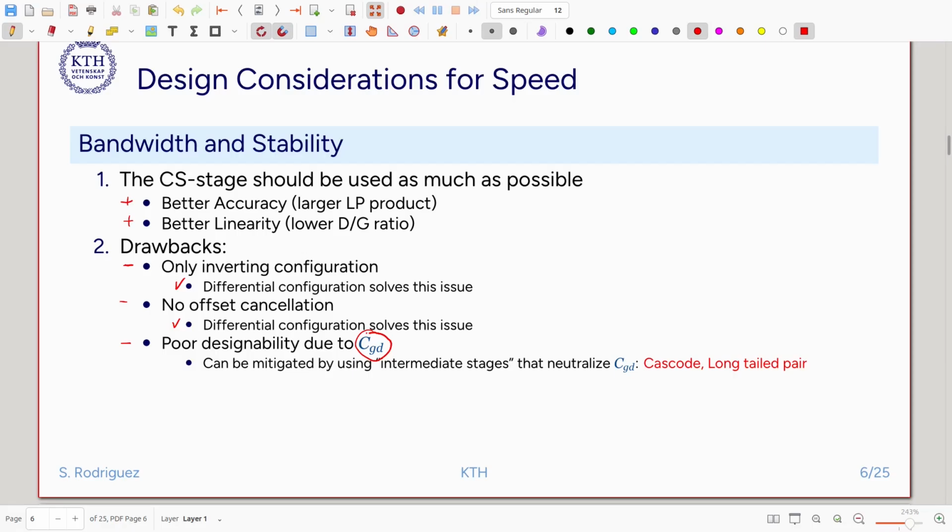It also introduces the Miller effect. And something that is very interesting is that even though this capacitor CGD is an overlap capacitance, that is very linear by definition, the moment that we multiply by the gain in order to find the total Miller capacitance, it becomes very non-linear, because the transconductance of the amplifier and maybe the output resistance as well might be non-linear.